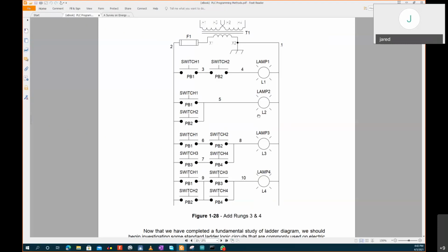Relays have two types of contacts, normally closed and normally open, and we saw the differences between them. If a sensor relay is powered and it's normally closed, it will definitely go normally open, and if it's normally open, it goes closed. So some logic interpretation you need to understand. That's what we captured yesterday.